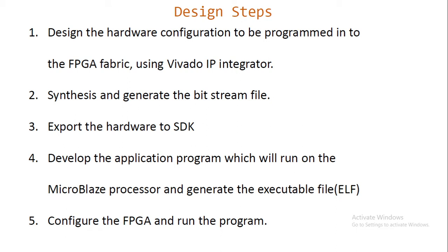So in this case, we will be developing a small program just to demonstrate the functionality of MicroBlaze. We'll be just printing a message on the UART console. After this, we will try to configure the FPGA with the bitstream file and the executable file generated from the SDK, and we will see the output. So this is the plan.